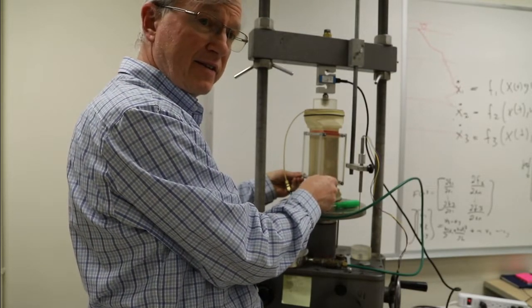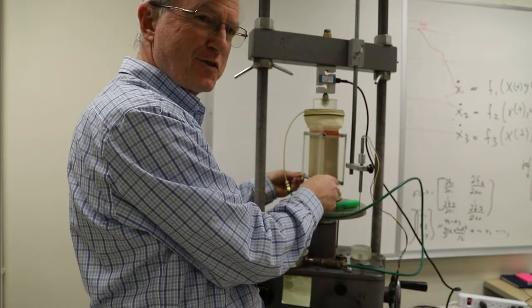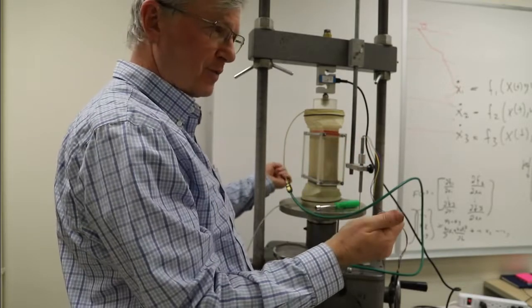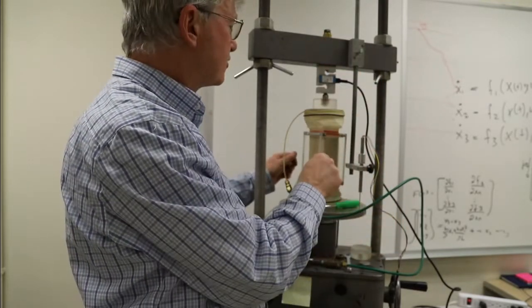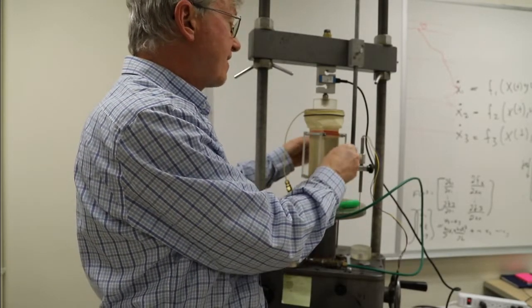have strain gauges. So in order to prevent that strain in the epsilon 2 direction, right, the sample wants to deform laterally when you're squeezing it, so it tends to pull and put these 4 tie rods into tension.